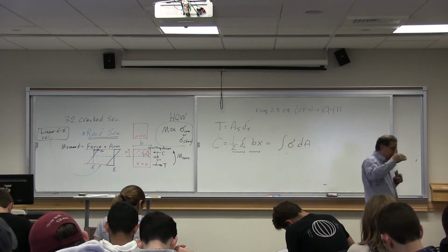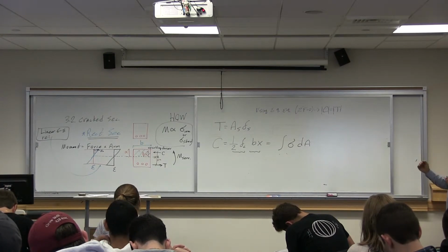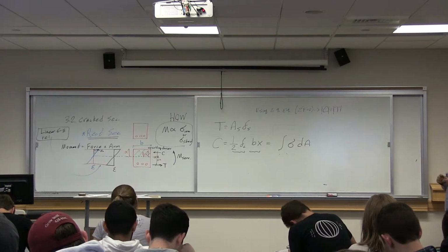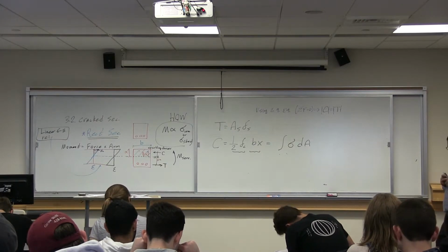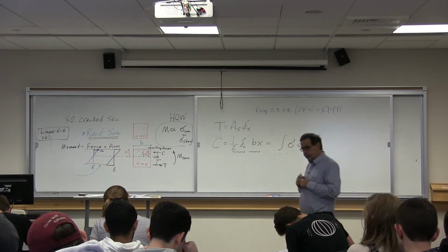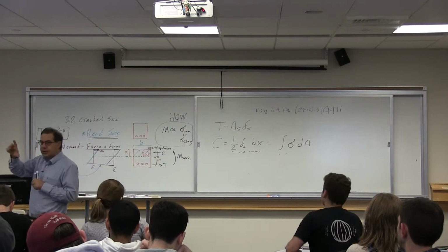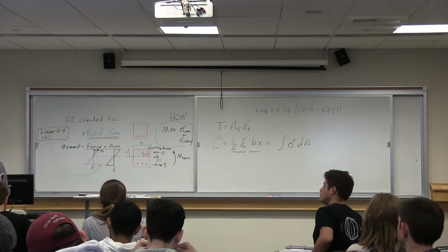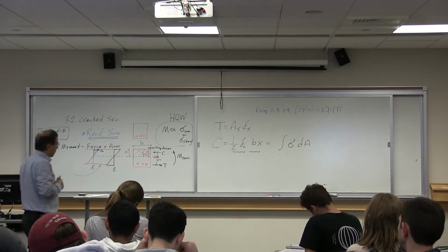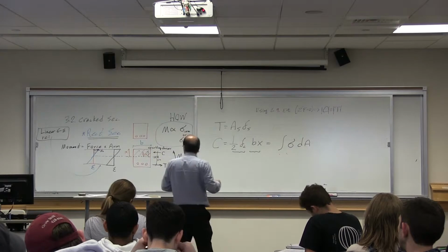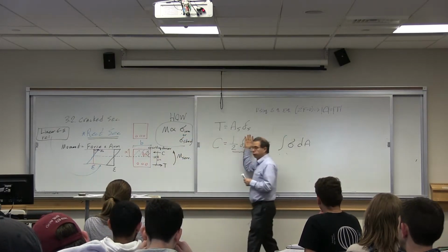So if you consider maximum compressive stress and linear variation of stress within the depth of the section, this is your compressive force. But the location is not at mid-height. The force is 1/2; the location is at 2/3 from the neutral axis. We took care of the force.